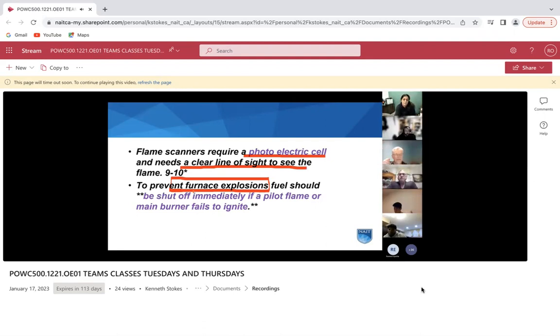Or fooling around with controls and interlocks. Somebody's inside of a panel with a screwdriver pushing on relays, trying to get things to run in a hurry. Ignition occurs when those passages are full of gas. That could be a furnace explosion, and that's not the same as a boiler explosion. It's an explosion in the boiler furnace, but it's an explosion of fuel in the furnace, as opposed to a pressure part explosion. Okay.